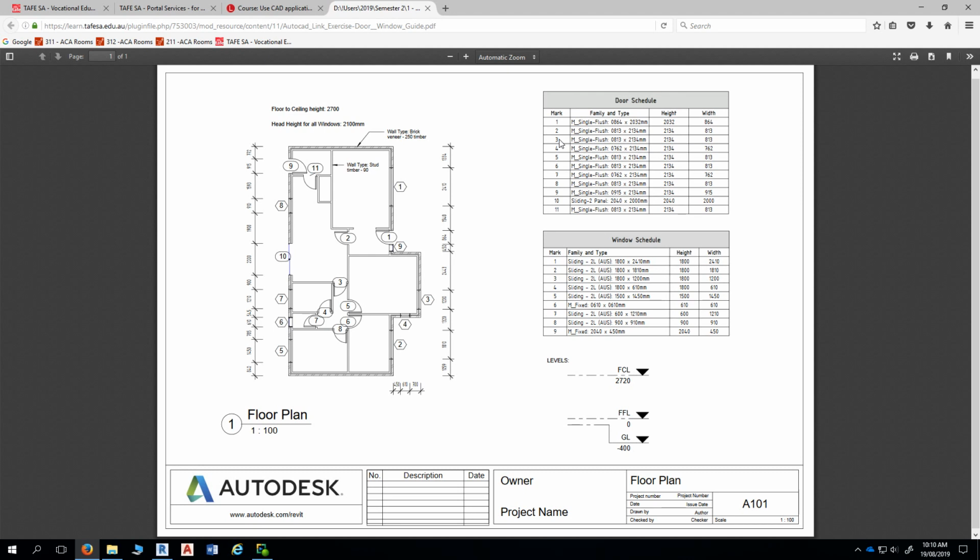Yeah, so in the first instance you may have to load a family into the project, mainly the windows, but to create a different size of window, a custom size, how did you do that? Type selector, we went there and then we selected the window, then we edited the size for the height, and we made a duplicate, and then we went in and made the adjustments, and then we used that to then go and select.